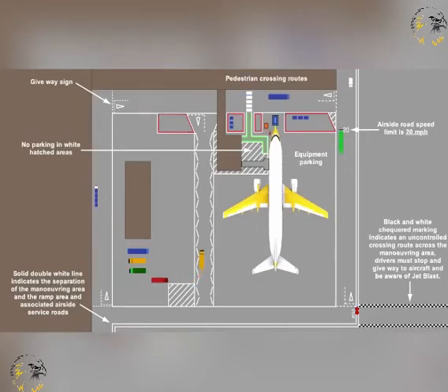The final consideration when looking at taxiways is that of vehicular integration. A road holding position is a designated place at which vehicles may be required to stop and wait, where taxiways are used as roads for vehicular traffic. The distance away from a runway centerline for such a hold is the same as that for aircraft holding positions. Normally there will be traffic lights at this vehicular hold.